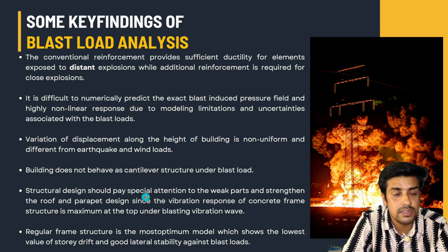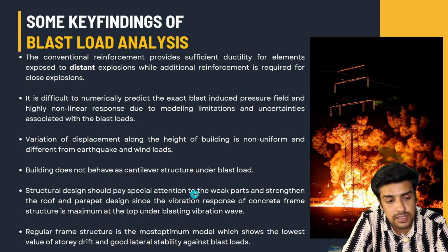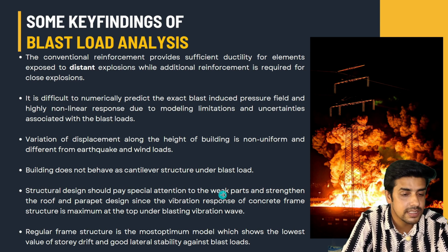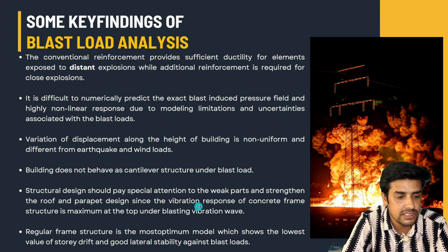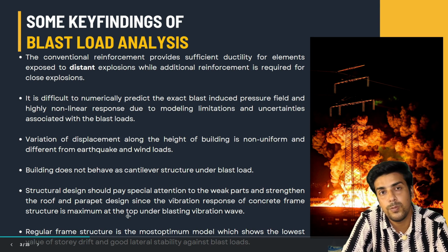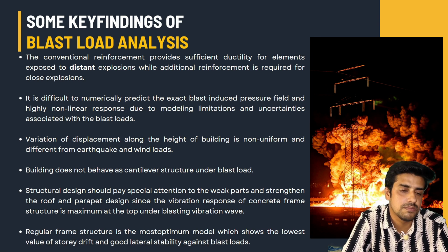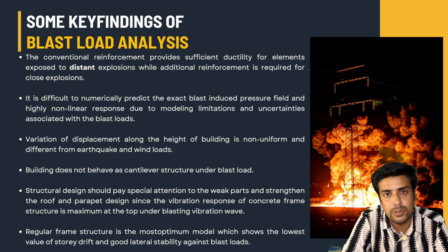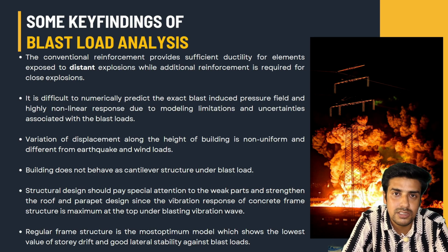Structural designers should pay special attention to the weak parts and strengthen the roof and the parapet design, since the vibration response of a concrete frame is maximum at the top under the blasting vibration wave. Everything is very unpredictable in this particular impact load case. So what we can do is check which parts of the building require more reinforcement, or more concentration.